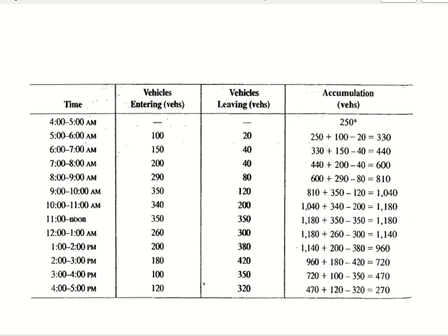If it is a commercial and mall area, then in the afternoon or something, when many people don't come, because some of the malls are only closed for 2 hours of the day, right? So you try to start when the activities have not started. Why? Because at that time vehicles entering and vehicles leaving will be very few, so your starting count will be accurate and convenient, because not too much change is happening.